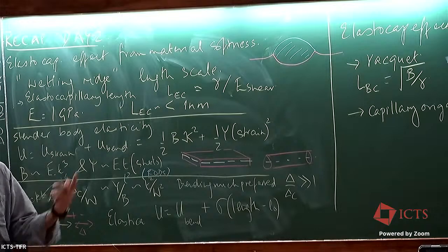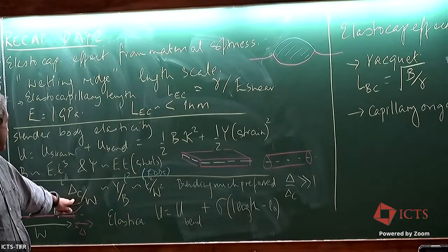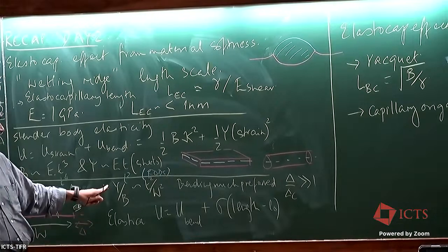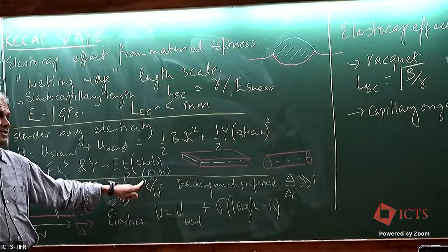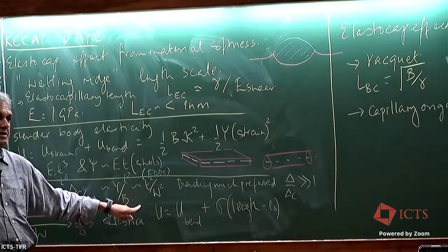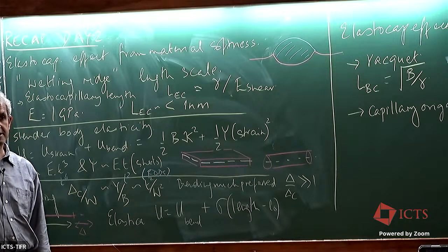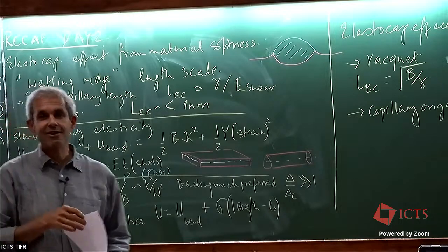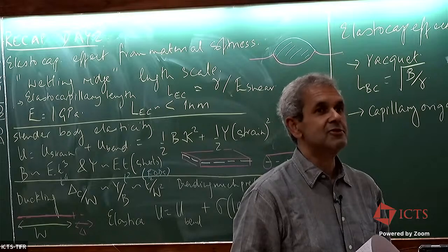The place where these two extreme possibilities become comparable in scale is a critical value, scaled by the size of this object, which goes as the stretching divided by the bending. This is thickness squared divided by dimension squared. So for something like this, that's a very, very tiny number.